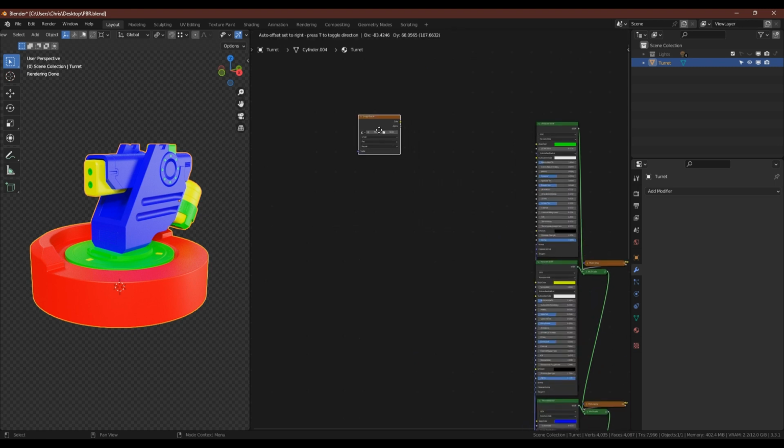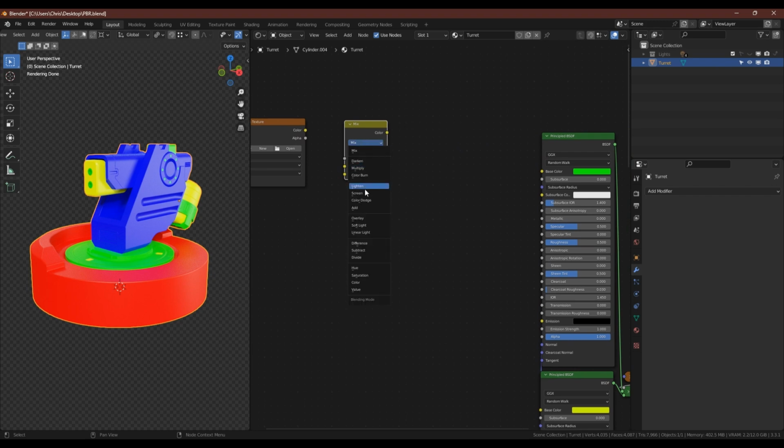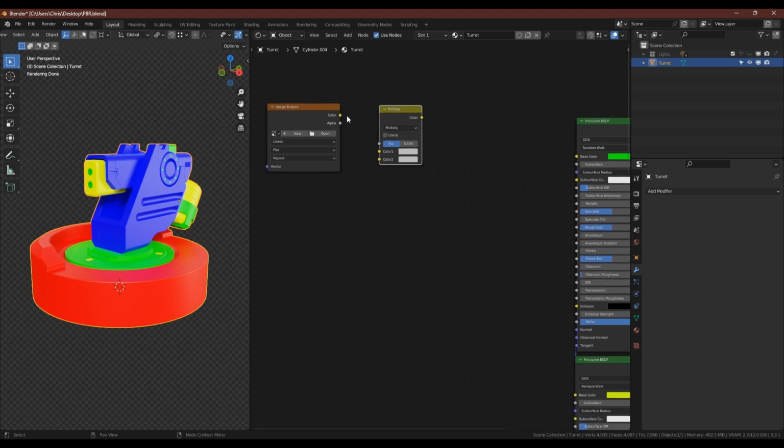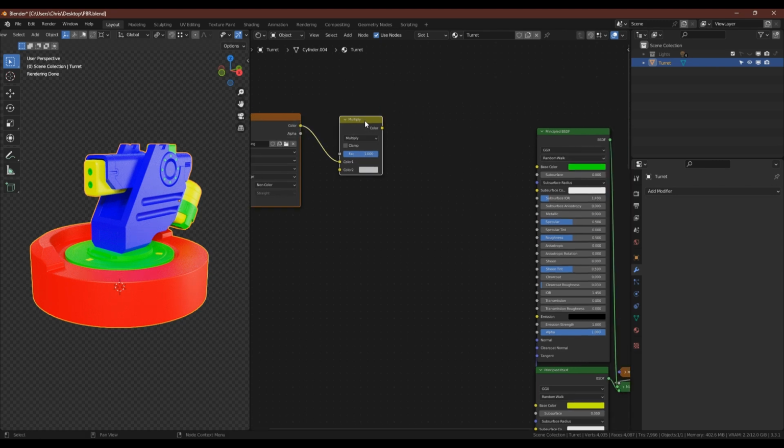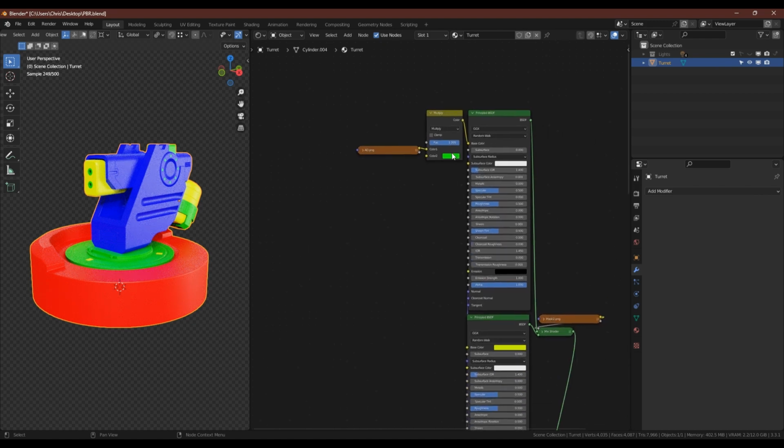We can do this as well for the ambient occlusion map we've got, through a mix shader. We could also crunch this with a color ramp if we want to turn the effect up or down, but for now I'm just going to put in the base ambient occlusion map that we've got, again with non-color. Put that into the first color slot, set the mix shader to multiply it as a factor of 1, and if we copy in the base color that we've currently got, which is green, you'll see when I plug this in, it literally just adds the ambient occlusion to all the green parts.